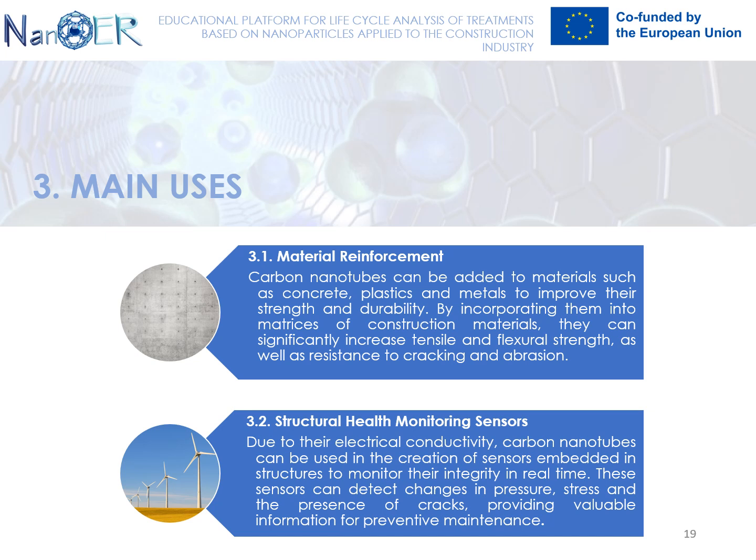Also, the flowability of the concrete is reduced considering that CNTs have a high aspect ratio, leading to the formation of clusters which prevent the movement of the concrete particles. Another factor that improves the strength of concrete is the ability of the CNTs to form strong bonds with the paste and enable bridging. The thermal conductivity of concrete is also enhanced by CNTs at extreme temperatures.